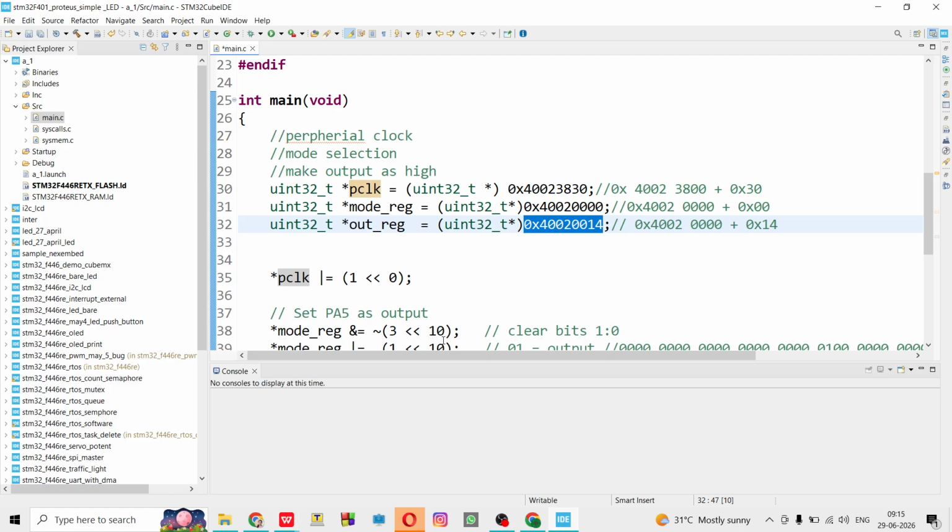So this is done here. I am enabling the 0th bit. This is the 0th bit, and which value am I going to assign? 1. And we already know how to set a bit. If you don't know, kindly go through the bit manipulation video which is on our channel itself. In order to set the value, we have to do an OR operation.